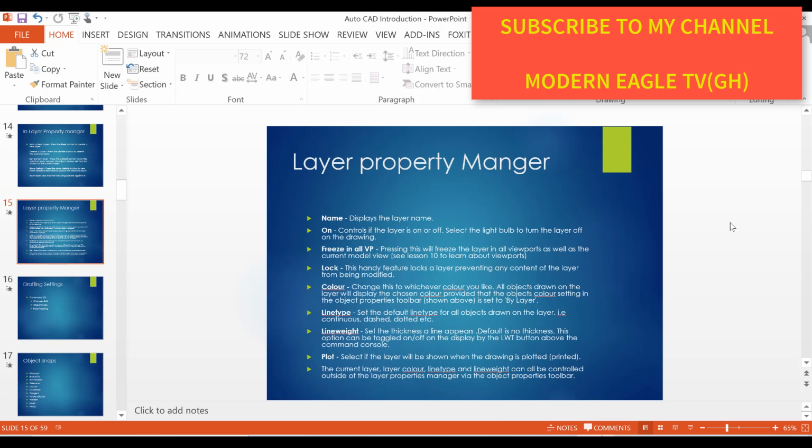Plot: select if the layer will be shown when the drawing is plotted, printed. The current layer color, line type, and line width can all be controlled outside of the Layer Properties Manager via the Object Properties toolbar.